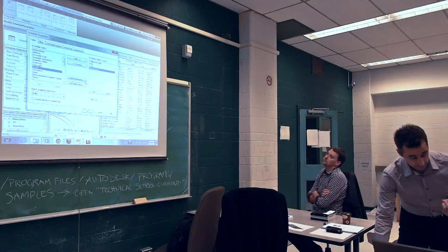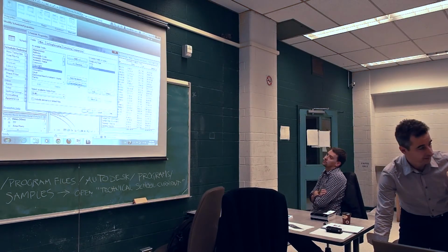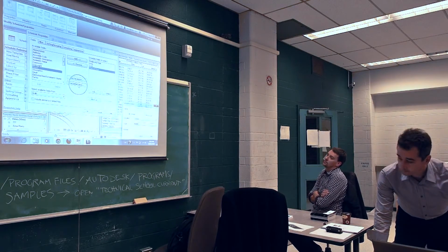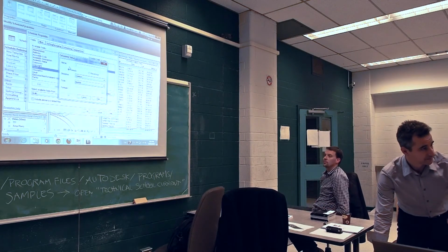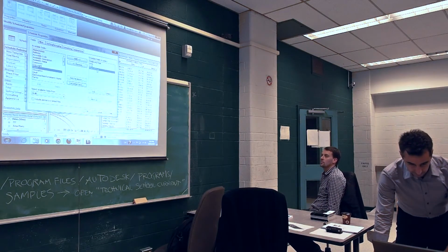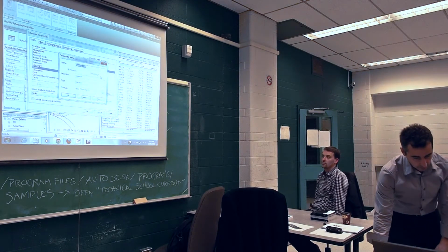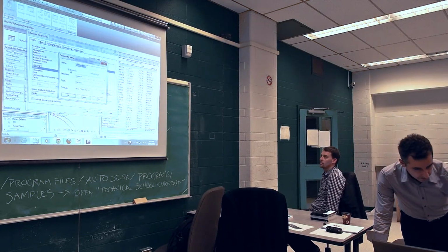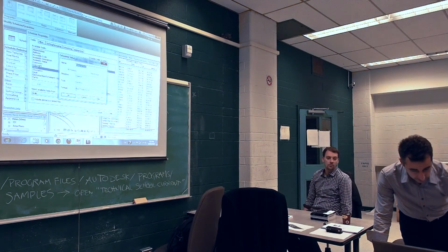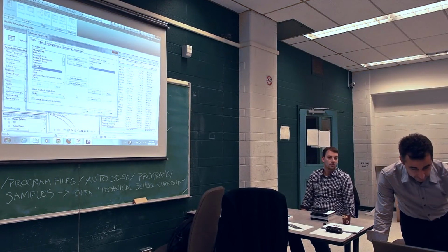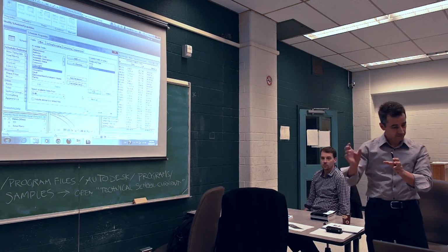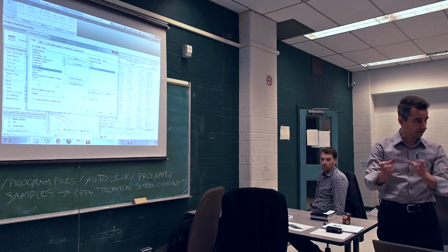So for that reason, if I don't have it but I need it, I can create a calculated value. This is it right there. And if I click on it, I'm presented with something like this. I can define it. Let's look at this material cost because I can also edit. So what is it? It is a formula which will list the type currency, and the formula is area multiplied by cost divided by 1 square meter, so it evens out the area and I only get the cost. So I'm going to have another column which will be populated when the cost and the area are populated.